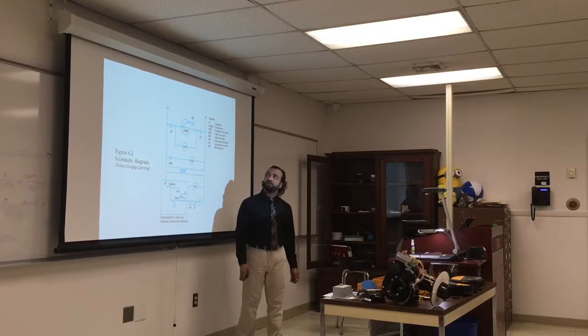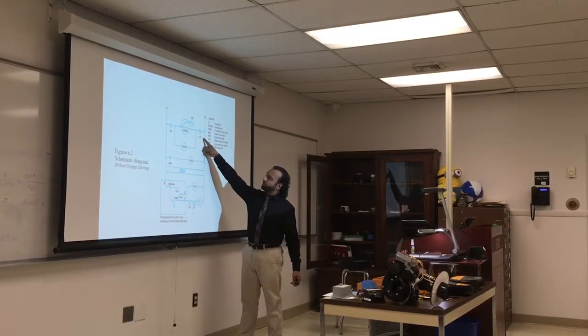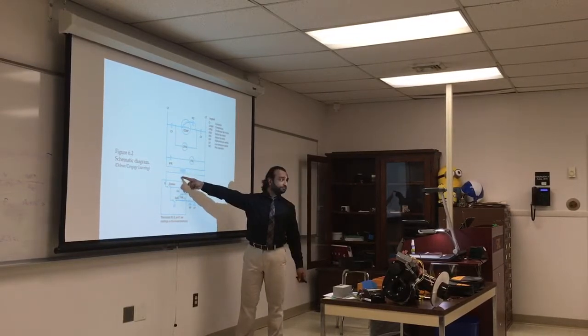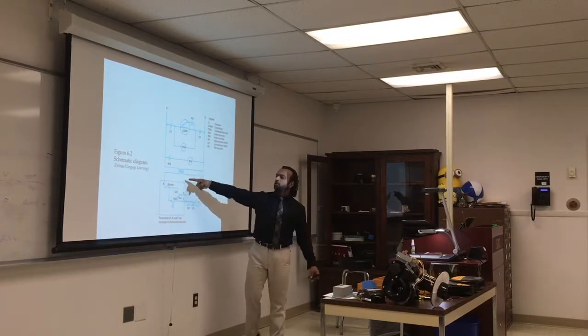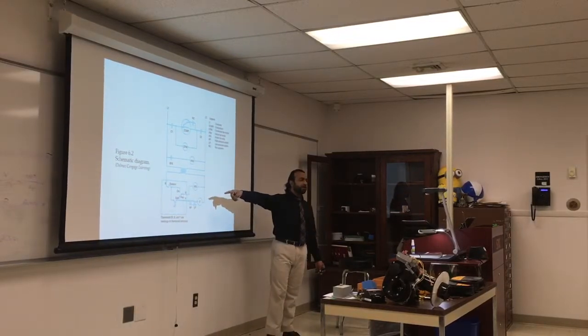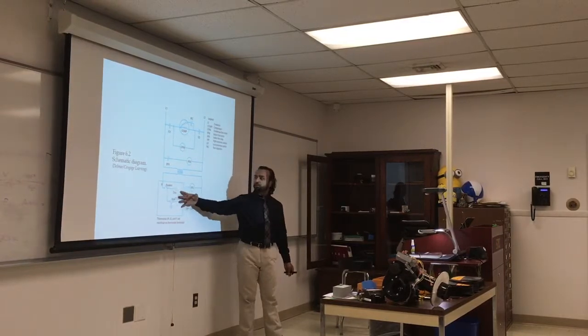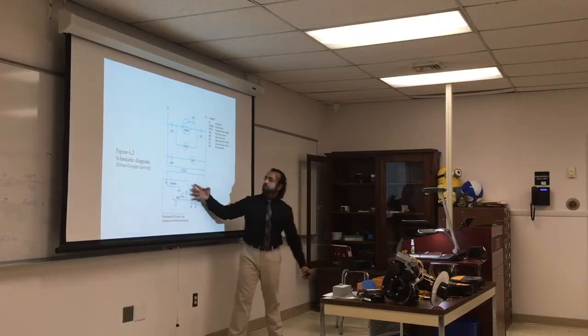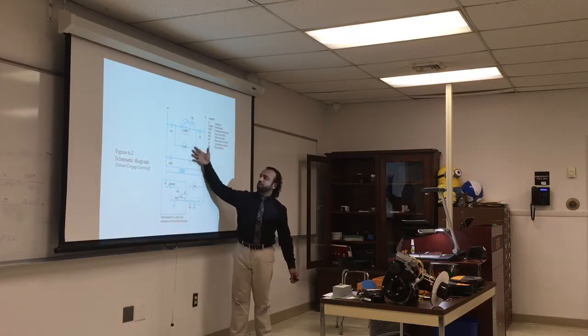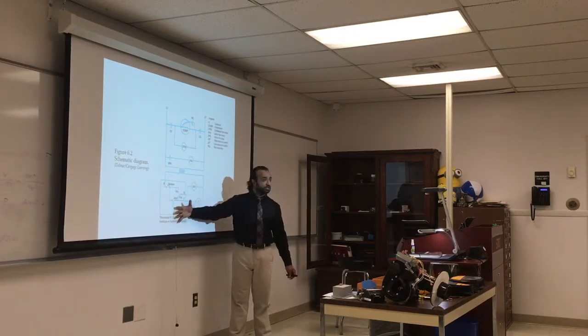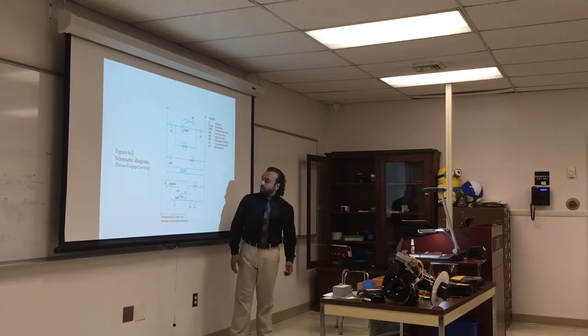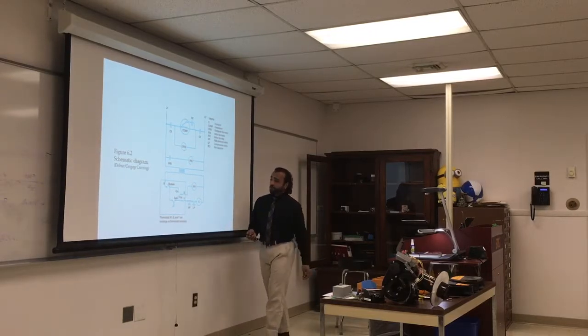No, it's not going to function properly. We have, what is this? A transformer. So if you have a transformer, what is the power going to be in this circuit? 24 volts, which we use for control. So again, what does that tell you? It tells you this is the power coming to the equipment, and this is the sub-circuit for the control. What does this look like?